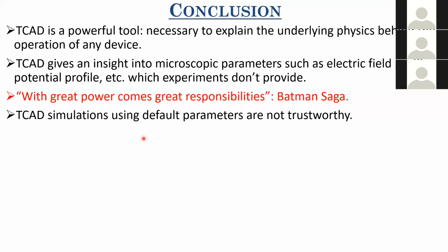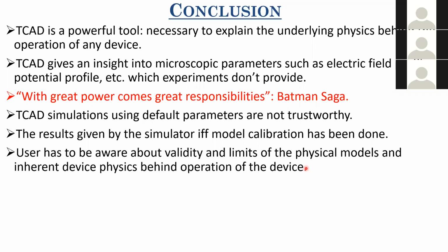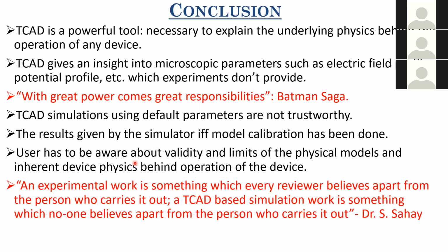And what are the main points there? So using default parameters, your TCAD simulations are not trustworthy. Also, the results given by your simulator are legitimate if and only if your model calibration has been done. Also, the user has to be aware of the validity and limits of the physical models and the inherent physical phenomena which are present in any device before going ahead with TCAD simulations.